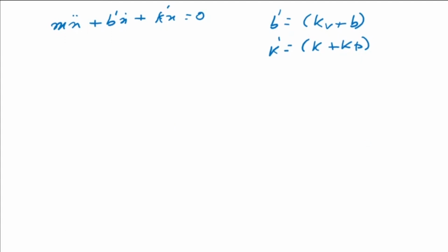What does that mean? You put a value of kp, assume critical damping, and then see the response of the system. If you're happy with that, then it's very good. If you're not happy with it, then you change the values. So this question of what is an optimal value of kp and kv, it may be optimal with respect to something, maybe overshoot, rise time, fall time. But then this question doesn't have much meaning because you have one equation and two unknowns. You can just keep varying them and get particular responses.